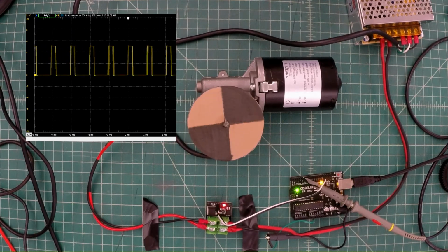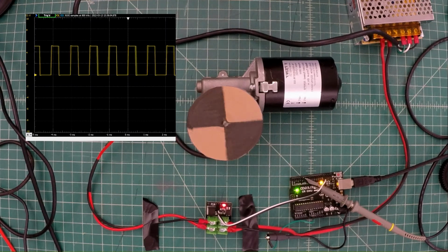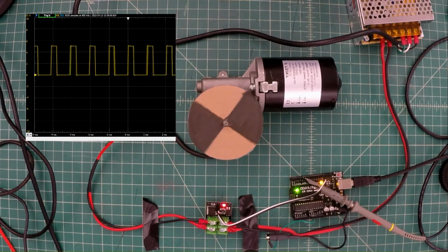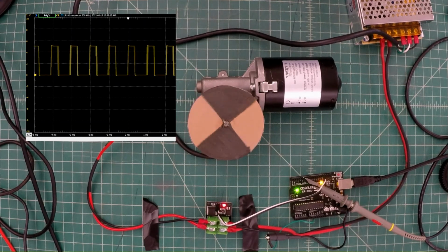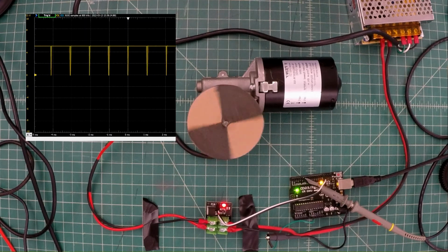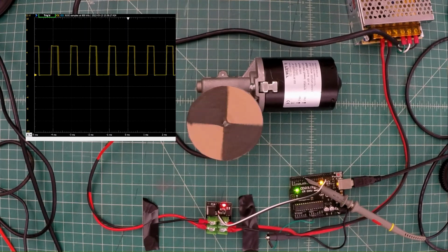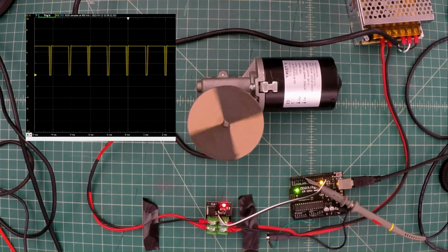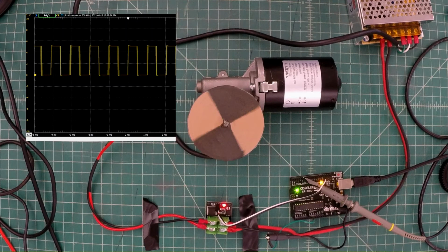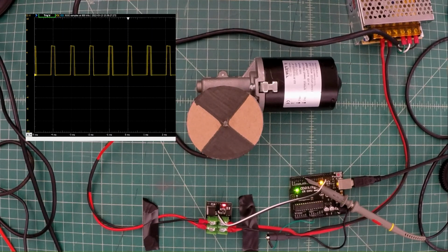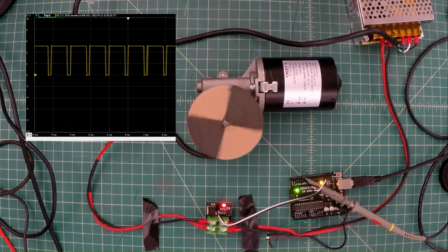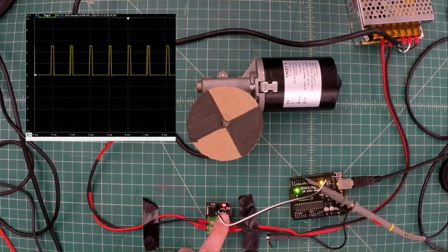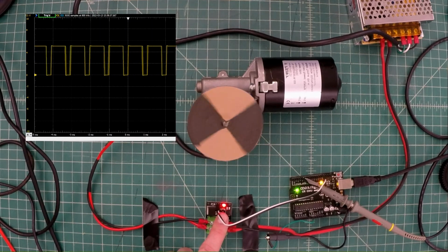So we can see as the pulse width modulation increases its duty cycle, the motor spins faster, and then it starts to spin slower until we come back to stopped. And we keep ramping back and forth there. So you should notice that when the duty cycle is high, we see the motor spinning quickly, and then it ramps back down. When the duty cycle is low, the motor is spinning slowly until it's stopped when the duty cycle is really, really low.